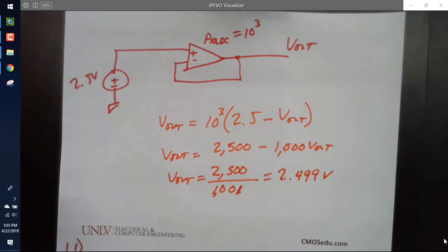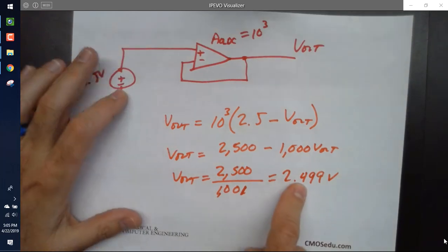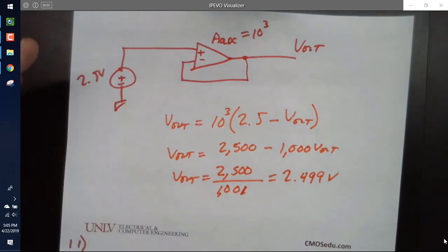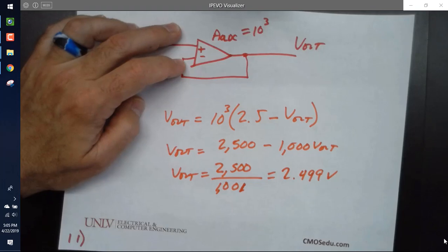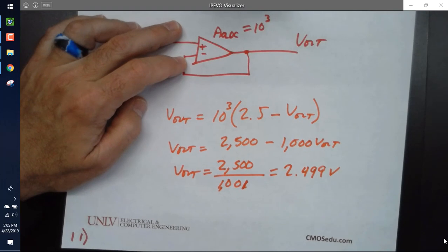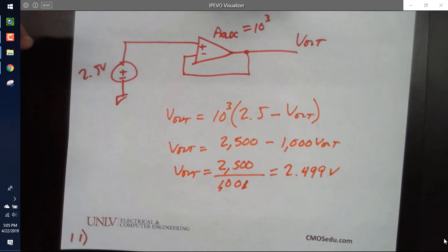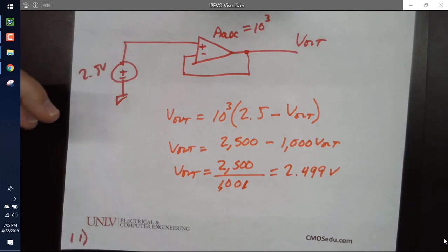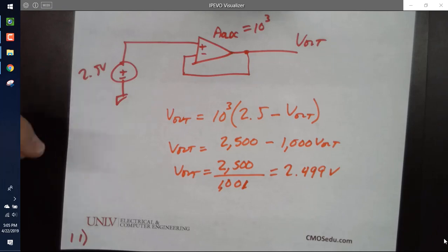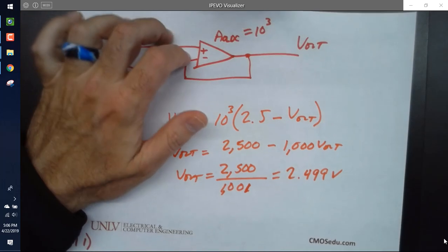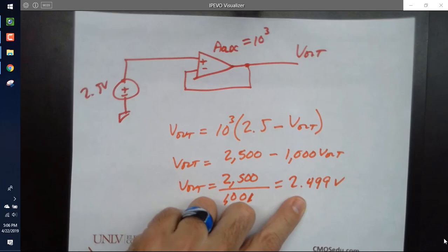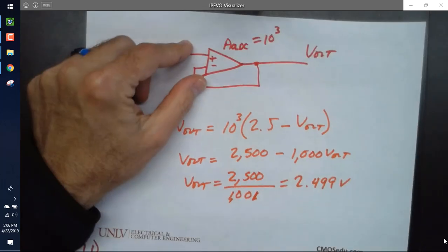Does everybody see that? What happens if the gain drops even more? Say it's 500. For analyzing circuits, you can treat it like an ideal op amp where these two are the same voltage. Right? That makes sense? I guess the key takeaway is they're not. In real op amps, they're not the same voltage. Now, again, when we come back next time, I'm going to show you that when I beef up the output transistor, I'm going to get an offset here to make things work out. That's unrelated to this, but it's related to making sure the biasing is okay.